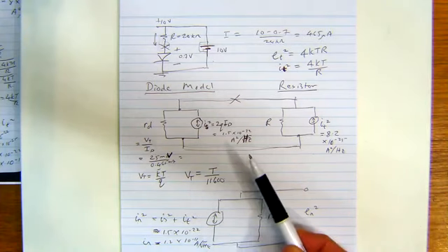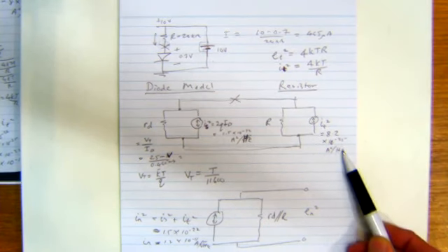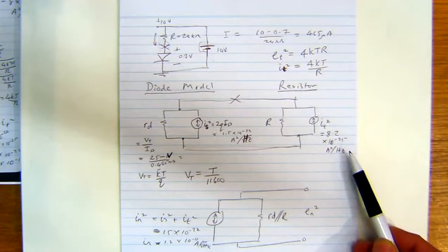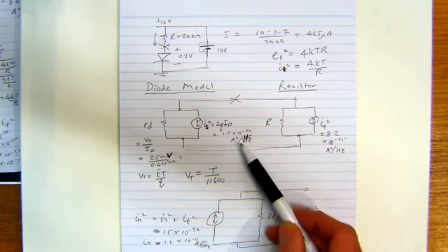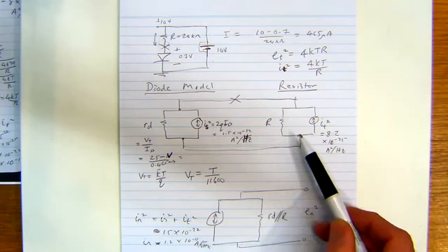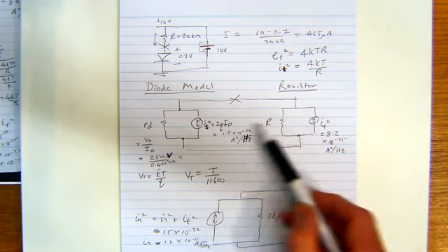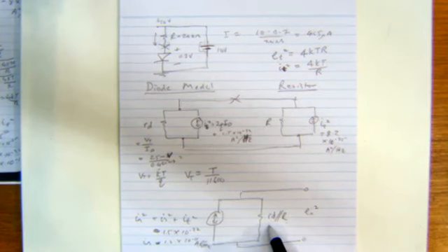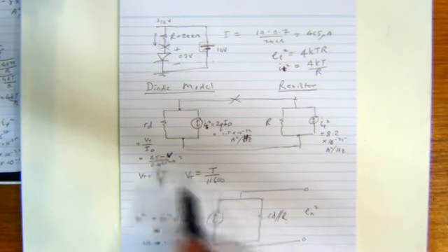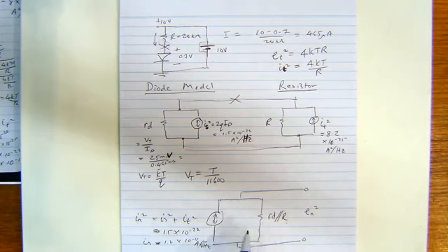So we can neglect the thermal noise. We can neglect the thermal noise of the resistor because it's smaller than the shot noise of the diode, and we can probably ignore the resistor itself because it's much larger than the incremental resistance RD of the diode.